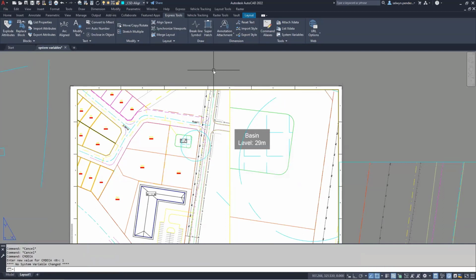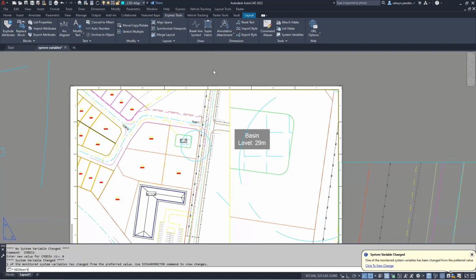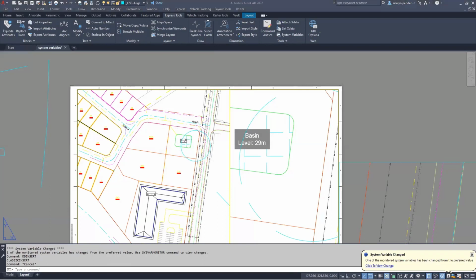Okay, there are certain dialog boxes offhand I cannot place. The plot one used to be one that I knew worked. DDINSERT was another one. Anyway, I think this is one of those where you find that you are inadvertently operating through the command line and you don't know why the command doesn't prompt. So at least if you know to type CMDDIA, flicking the switch on this particular one can normally be the solution that you're after.